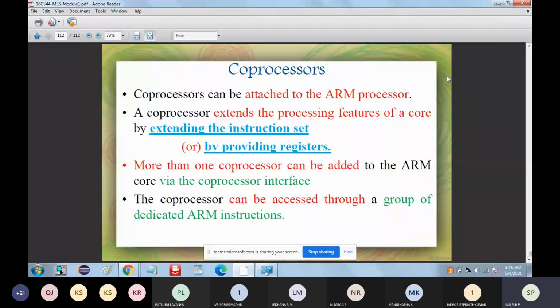So when you have the ARM dedicated instruction to access the coprocessor, at the decode stage, if it sees that the instruction being run is a coprocessor instruction, it offers it to the relevant coprocessor. Now if that particular coprocessor is not present, or it doesn't recognize the instruction, what type of exception is it going to take? Yesterday we discussed that you have different types of exceptions, right?